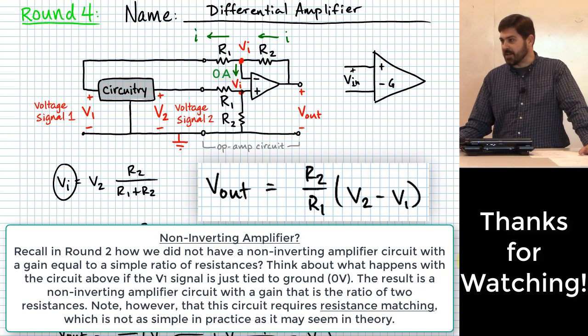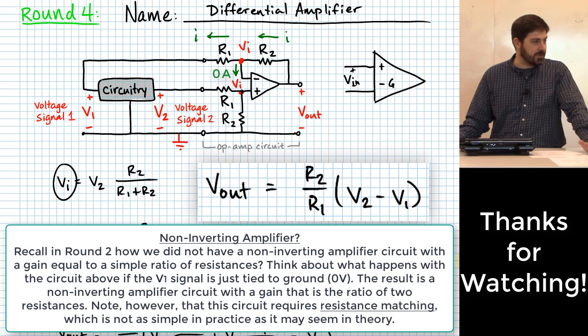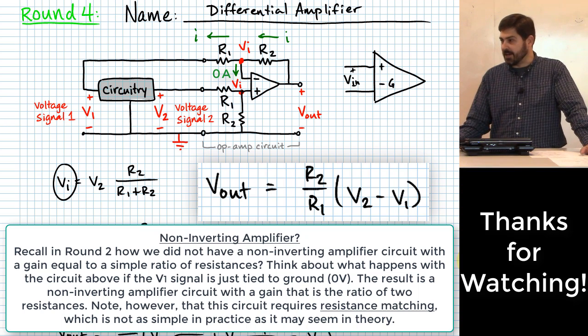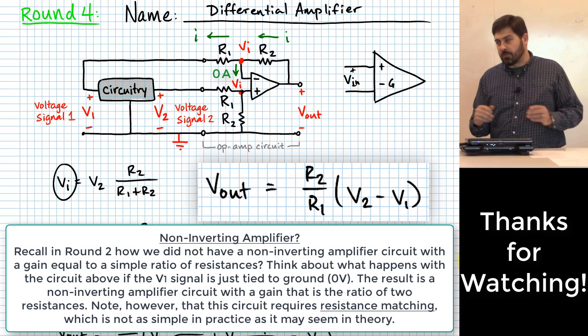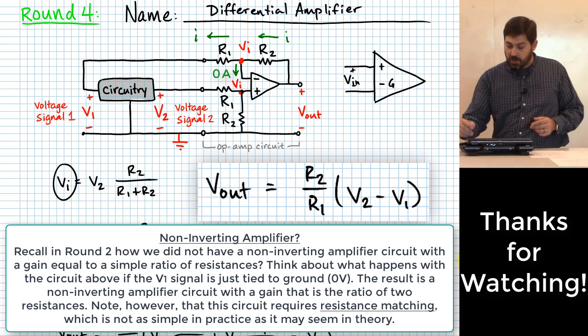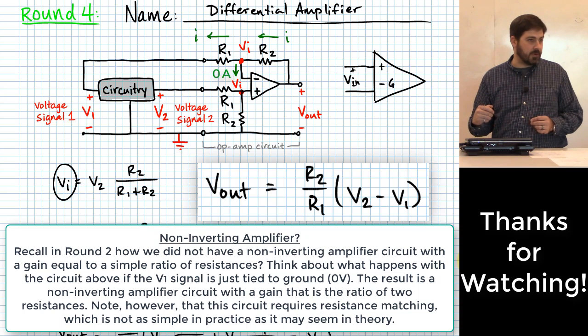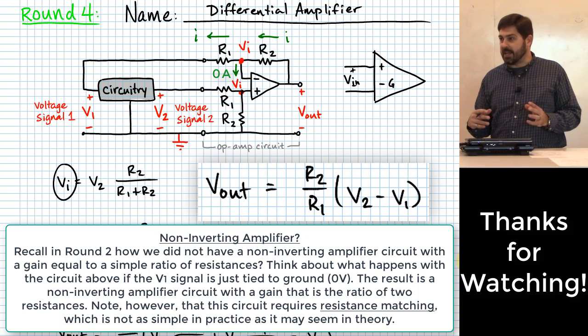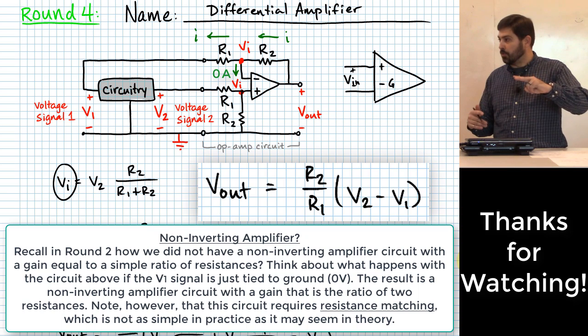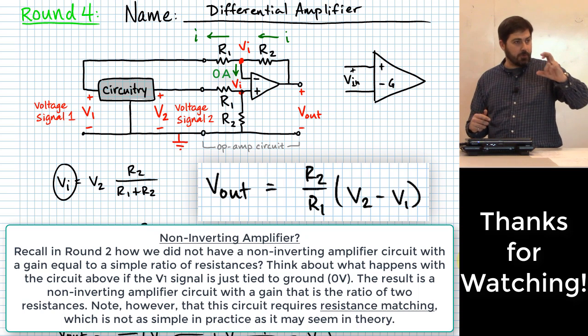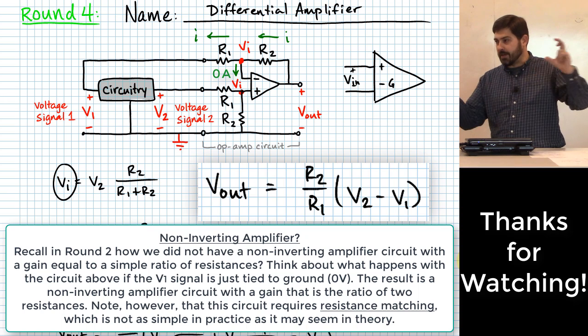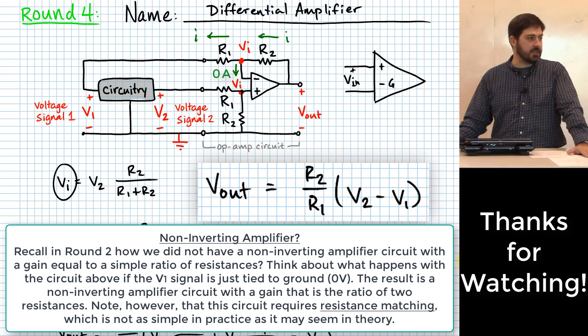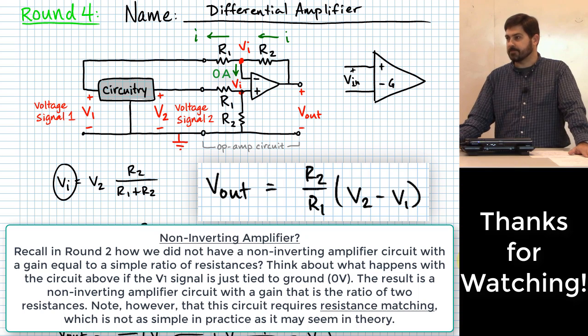Cool. All right, so that is the end of what I was planning on doing today for this talk. We might at some point look at some more op-amp circuits, but the main point, just to reiterate it one more time, is not that you memorize what all these op-amp circuits do. The main point is that you know how to get into them, and by applying those two rules, no current on the inputs and no voltage across the inputs, you can analyze a whole bunch of different kinds of circuits, and you don't have to memorize the formulas. Okay? Fantastic.